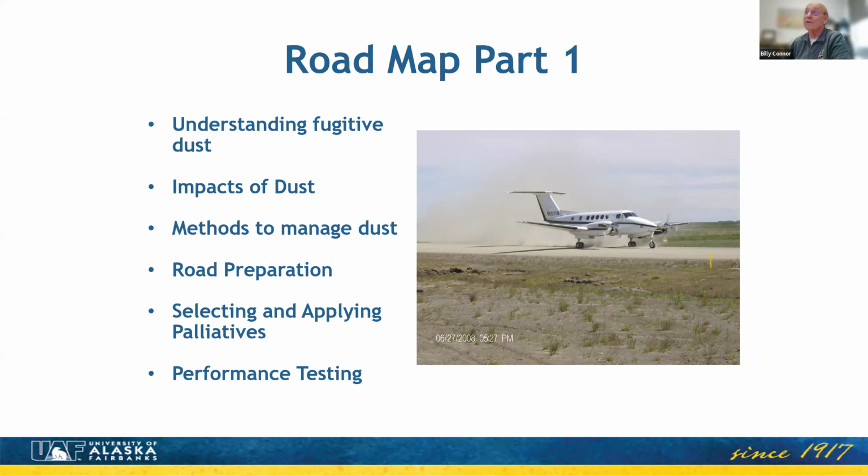First, we talked about what dust is and why we were concerned about it, the impacts of dust, and the methods of managing the dust in a number of different ways. Of course, always one thing that we always want to do is prepare the road for the application of palliatives. And we talked a bit about selecting and applying those palliatives, primarily things like calcium chloride, water, and synthetic fluids. And then we talked about how we can measure the performance of the palliatives themselves.